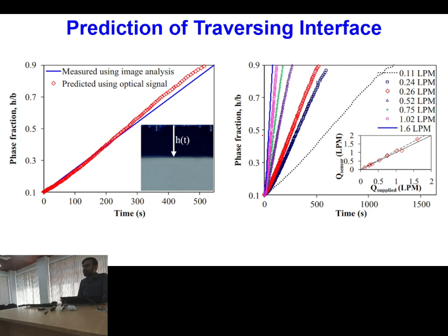In terms of flow rate sensitivity, we have seen in the previous curve that when we were jumping from one step to another, during that time when the interface was moving up and down, we were able to trace the continuous variation of the interface. That continuous variation of the interface, in a known diameter system or a constant cross section tank, can be utilized for measurement of fluctuations in the flow rates.